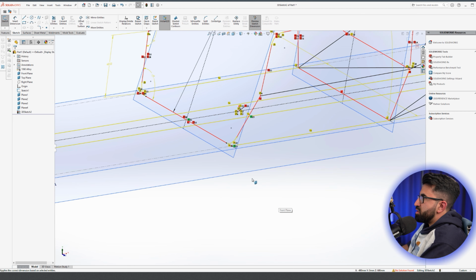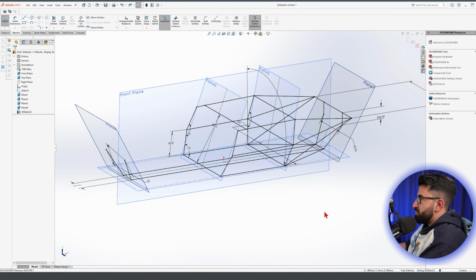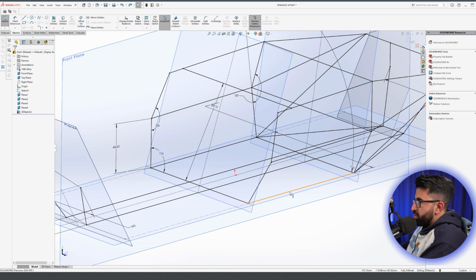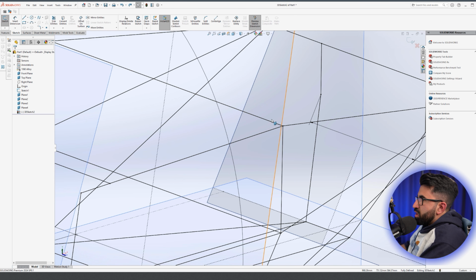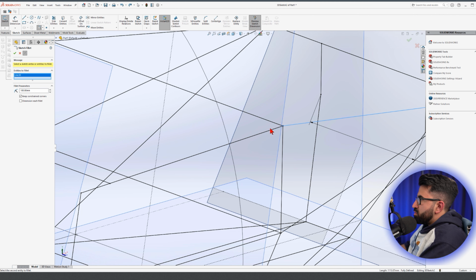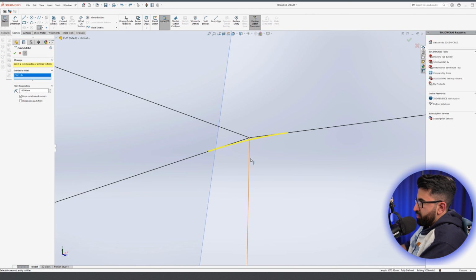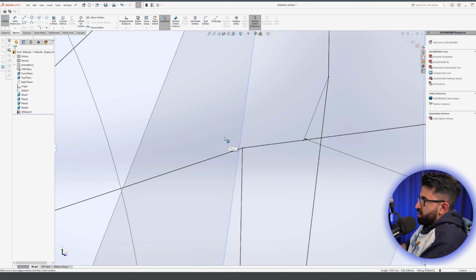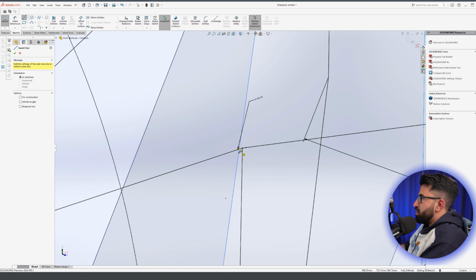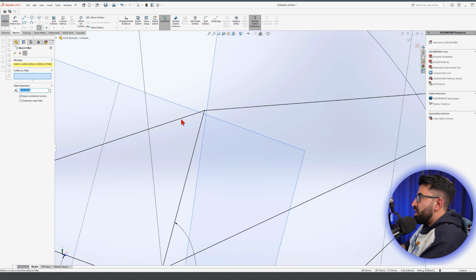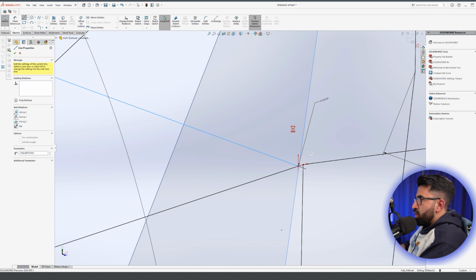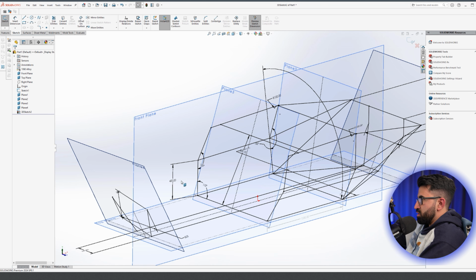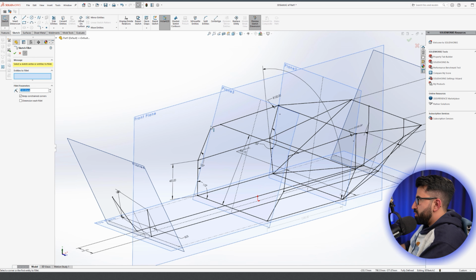When you have a situation like this, I would just redo this and try to take a different approach. I'm not sure if the problem was here, but if I wanted to do this, create so much problem. That one was critical. Let's do this one. Instead of just connecting these two lines together and then coming up here to round these two corners and create the bypass and therefore the problem, I would wait on drawing this line, do the bypass first, then come, actually I have to bypass the other side too, and then come and add the line later, one step later, like this. So something like this. Okay, so when you know rounding edges are going to cause problems like this, see, there's no problem this time, do it in that order.